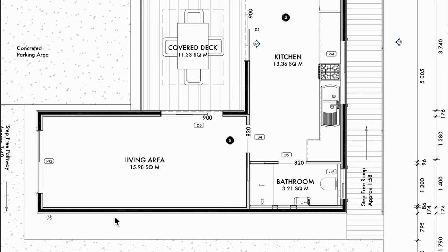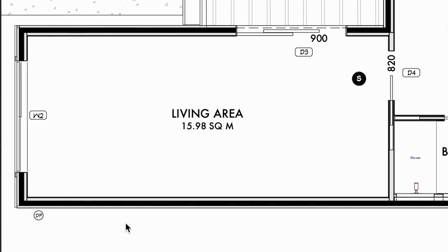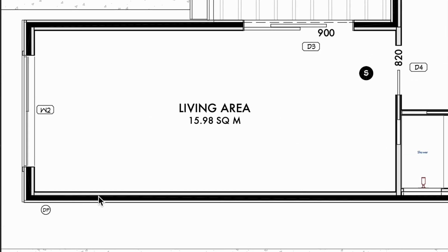So this is my end wall here, and what I'm calculating is going to be how many of those frames are going to fit that inside line there. Because these are inside studs, this black line here is the other material, which is going to offset my interior studs to my exterior wall paneling.